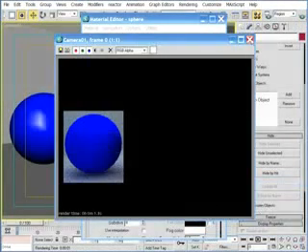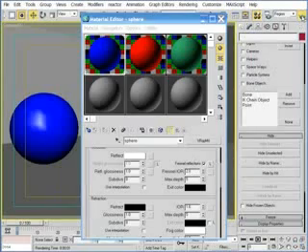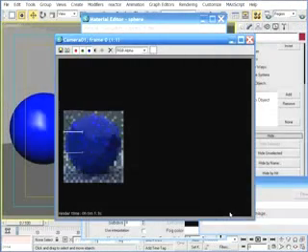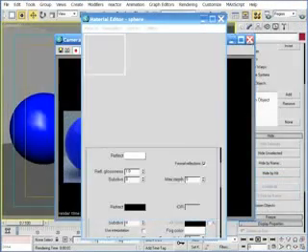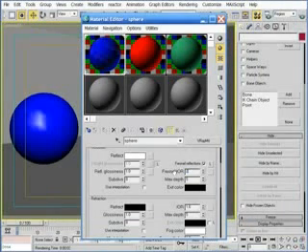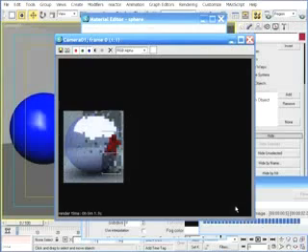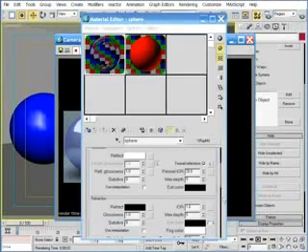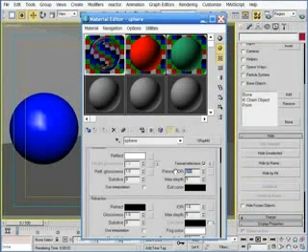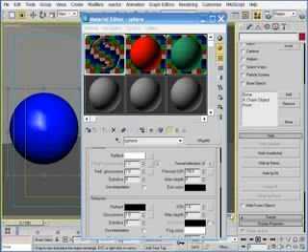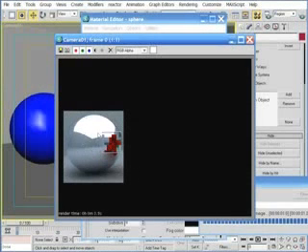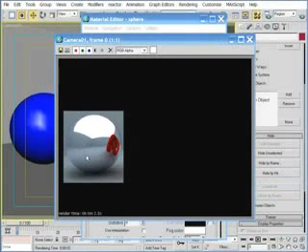I can also go in the opposite extreme. A value of 2.0 gives me strong reflections everywhere, but if I keep increasing the Fresnel effect above this point, or the index of refraction above this point, you can see that the reflections are getting so strong everywhere that I'm starting to lose my diffuse color and totally losing the Fresnel effect. In fact, I can continue to make the reflections so strong that the diffuse color totally disappears and my material returns to a perfectly reflective mirror, which finally happens when the Fresnel is set to 100, or the index of refraction.